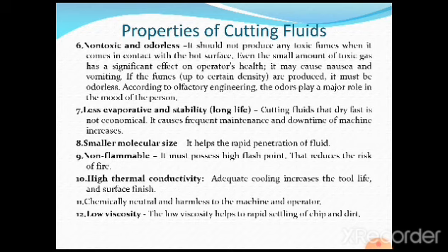Chemically neutral and harmless to the machine and operator, definitely. And the last one is low viscosity. This is very, very important. The low viscosity helps the rapid settling of chip and dirt. See what happens if the viscosity is more: it has a tendency to stick. So the sticking nature will increase if the viscosity is more.